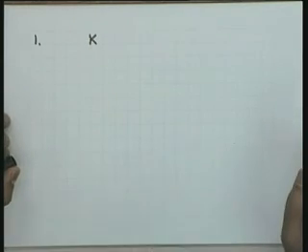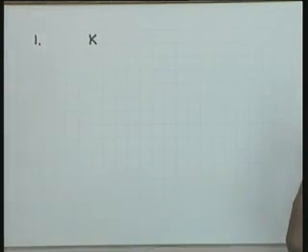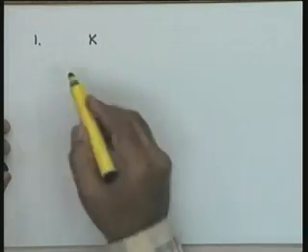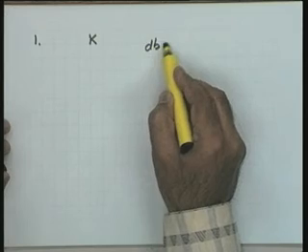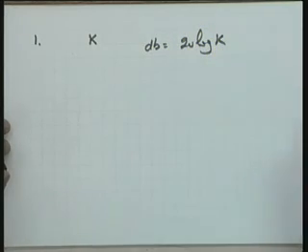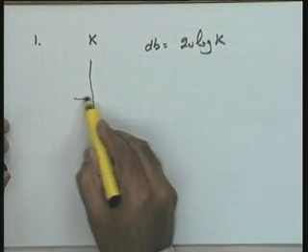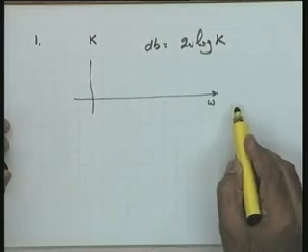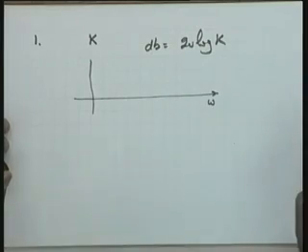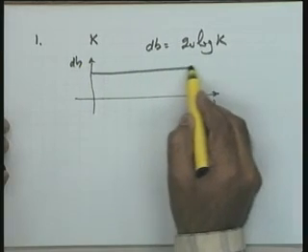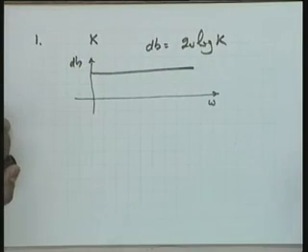So looking at the gain k, which may appear in any transfer function, you can see that if I convert this into magnitude, the decibels corresponding to gain k is equal to 20 log k. And this remains the same for all frequencies. So naturally, on a semi-log sheet, now as I told you yesterday, when I take this axis, it is definitely a semi-log paper, and on this it is dB, so it is going to be a horizontal line depending upon the gain k.